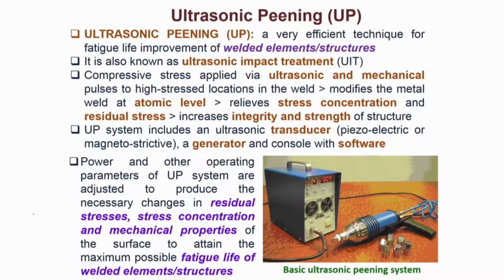In this particular lecture we are going to cover a very similar approach of conventional processing, but using not projectiles but very similar types of objects, solid objects, where the energy, or the velocity, is not coming from gas propelled or air propelled shots, but these kinetic energies are created by ultrasonic wave. So that's why this kind of process is called ultrasonic peening.